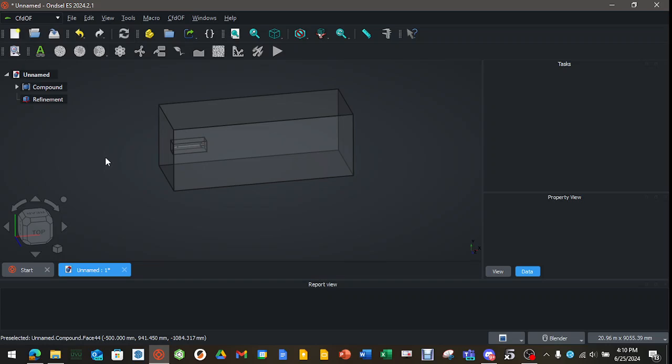And so eventually, pretty soon, hopefully in the next couple weeks, there'll be the freedom to create your boundaries first and then your mesh, versus create your mesh then your boundary. However, for today, and even in FreeCAD and other documentation I've read, it's always best just to kind of make the mesh first. I'll show you what I mean by that. But first, let's drop this analysis container and let's open it up. And let's go one step at a time.